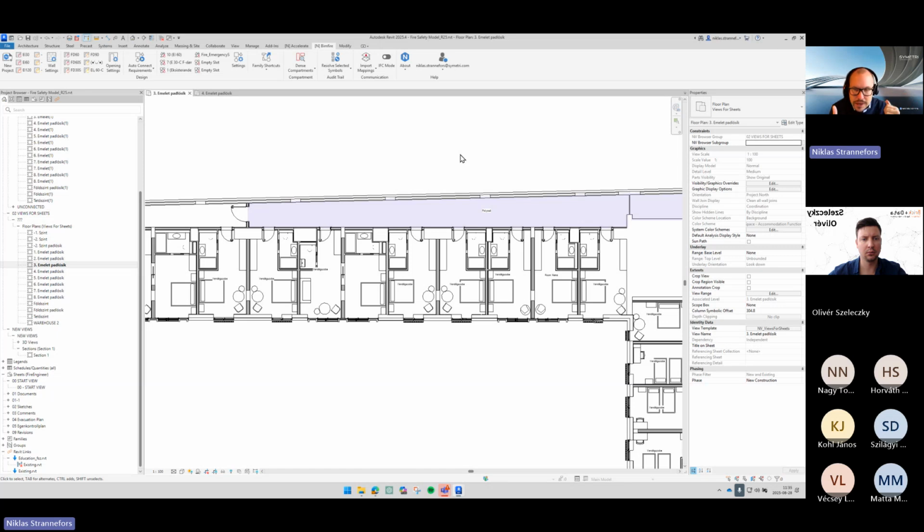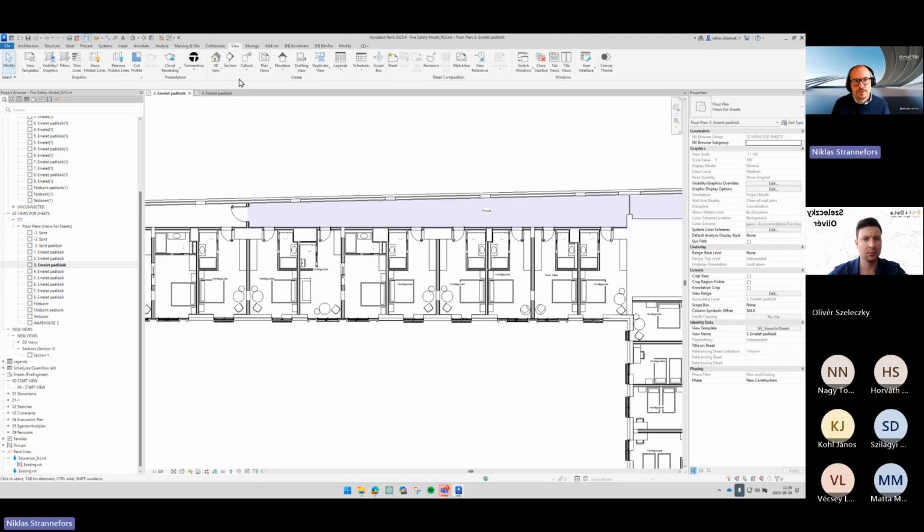The requirements that you see up there, the buttons, you can go there and click on those, but it's not meant to be clicked because it's going to take a lot of time changing tab all the time. So what I recommend everyone is to create their own keyboard shortcuts for this. That's why we have those as buttons, because we can assign keyboard shortcuts to all of them. And how we create our own keyboard shortcuts is super simple. We go to the View tab. We go to the far right-hand side. We have User Interface. And then on the very bottom, Keyboard Shortcuts.